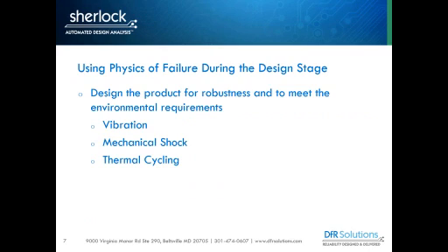Hopefully they're derating properly and making sure that their electronics can handle the current loads and the voltages being applied to them. But really, when something is missed, it's usually a mechanical reason. The board's not constrained right for vibration. It's experiencing too much deflection during mechanical shock, and it causes things to break. Or thermal cycling is causing early fatigue of our solder joints because we selected the wrong component.